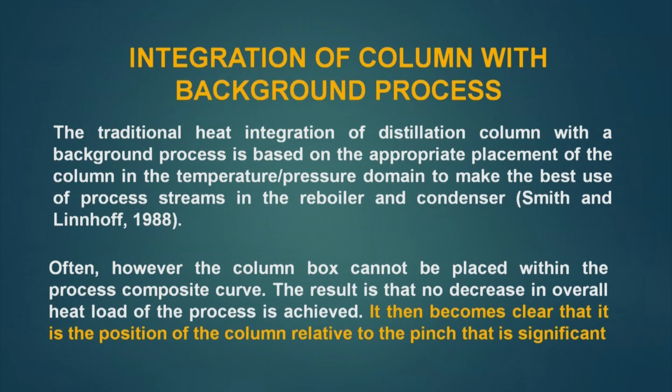This has been told by Smith and Linnhoff in 1988. Basically, the distillation column is working under two levels of temperature. Now, these two levels of temperature may be above the pinch of a process GCC, may be below the pinch of a process GCC, or may be across the pinch of a process GCC.